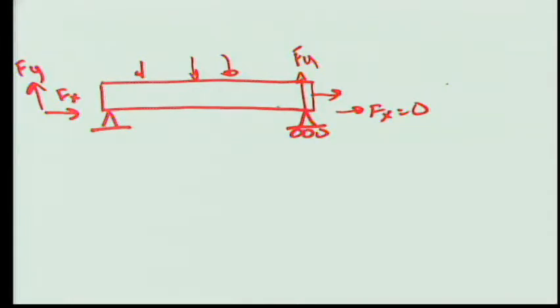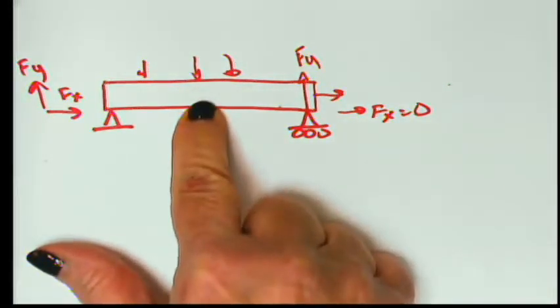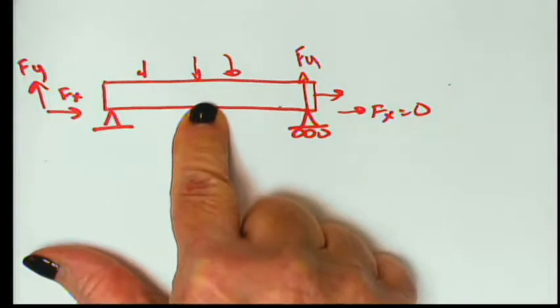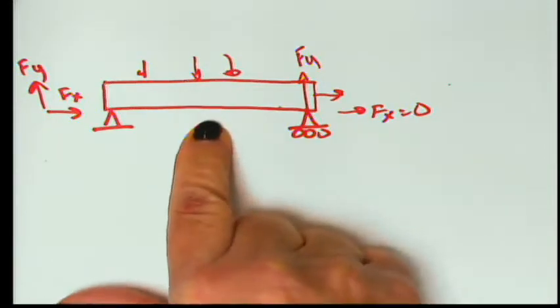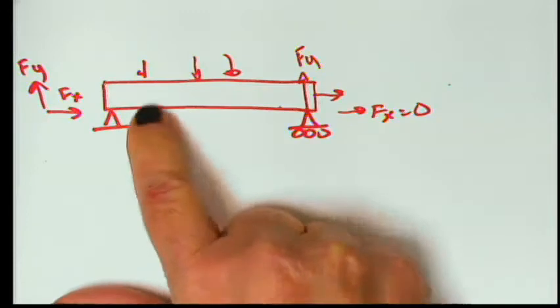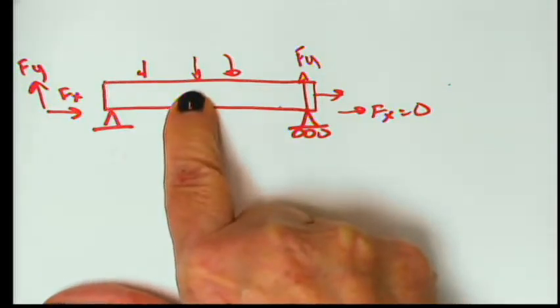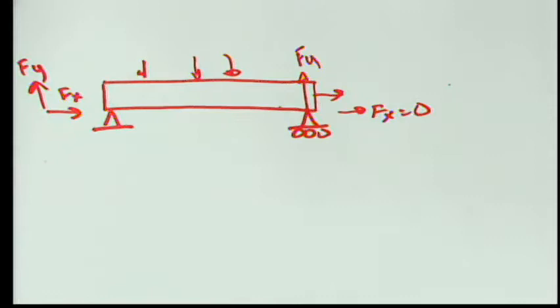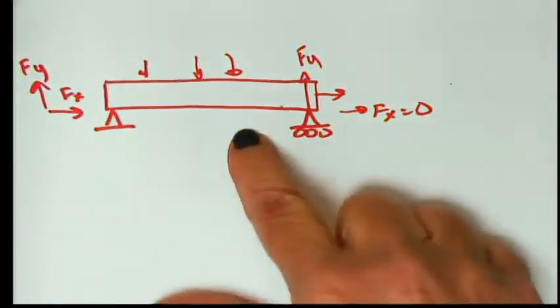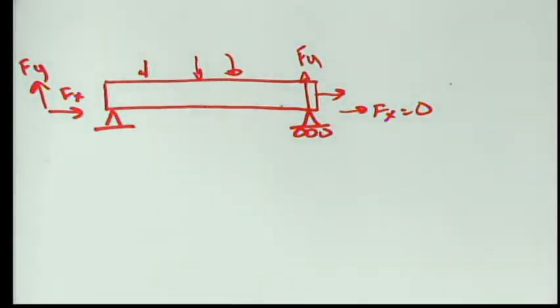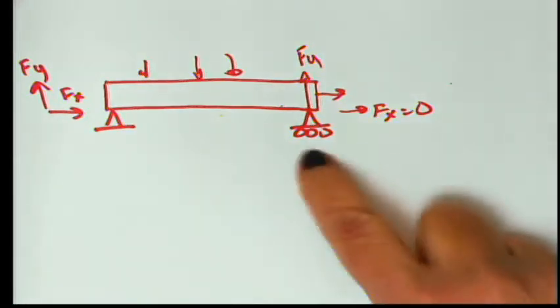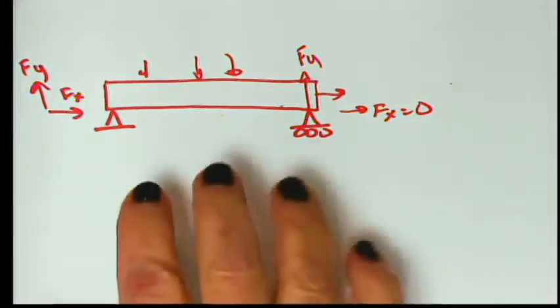And this is actually something that happens with bridges. If you look at any sort of a bridge, as you load them, they will expand or contract, depending on if they take on a significant U shape as they're loaded. And also, as they get hotter and colder, they'll expand or contract. So bridges will have expansion joints or rolling supports in order to prevent them from buckling and damaging the structure. So even though this is a simplified version, it is definitely a real situation.